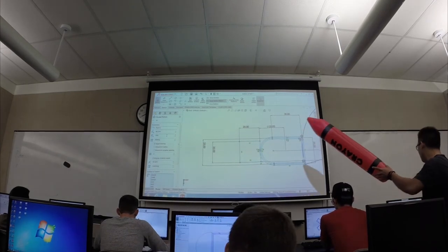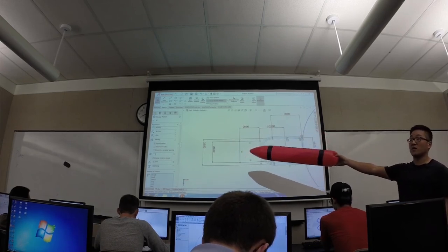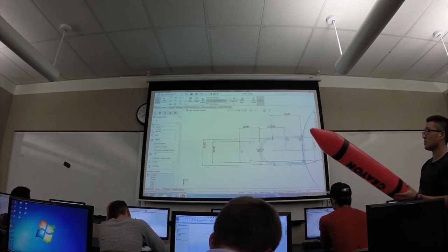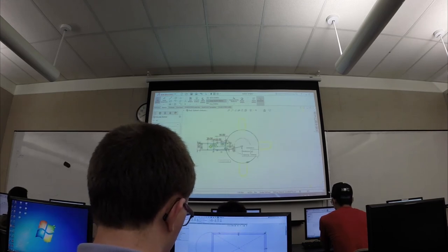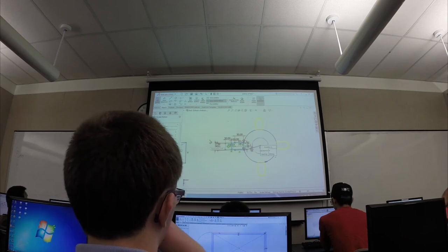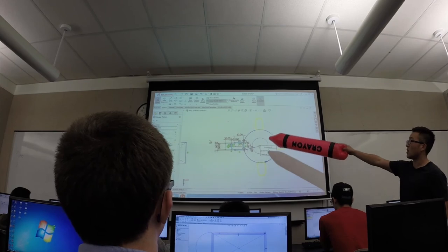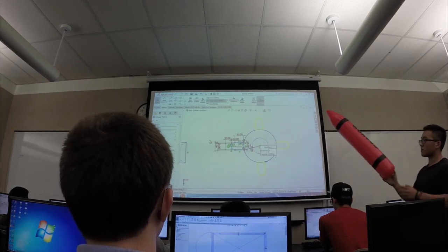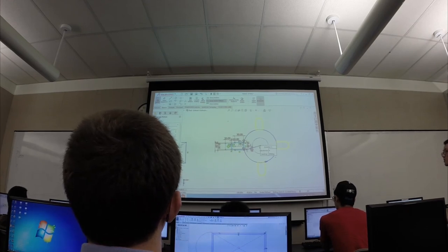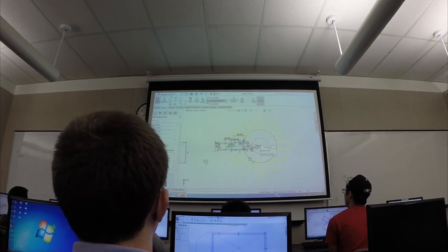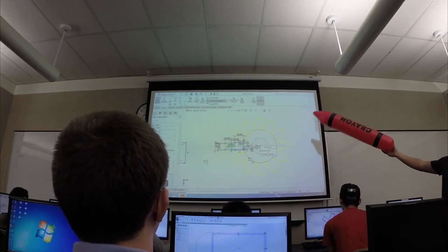And then this parameter right here lets you define how many times you want to copy and paste it, right? So we have it set to 4. So you notice that it previews, okay, this is where your 4 copy-pasted sketches are going to be. Let's bump that number up to like 12. And now it projects 12 instances of that sketch being thrown in there.